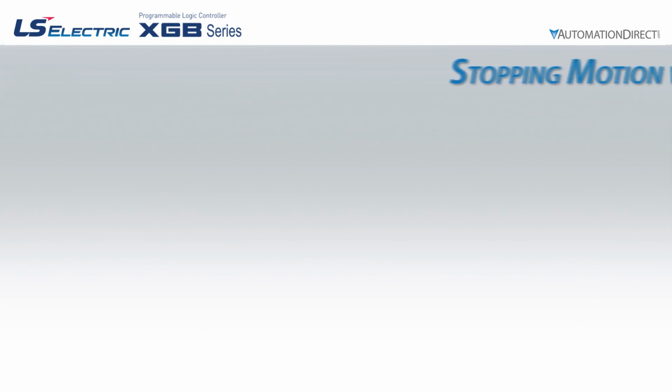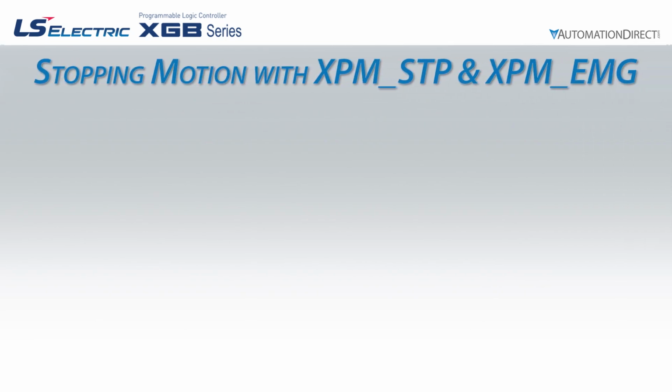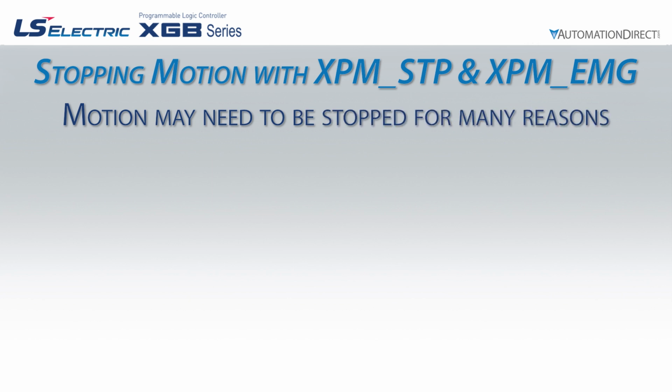Often during motion, we may want to quickly stop an axis. During testing, this might be to prevent a crash. During troubleshooting, it might be to catch a fleeting sensor or noise signal. Whatever the reason, the XGB PLC can stop any motion move using the XPM_STP or XPM_EMG function blocks.